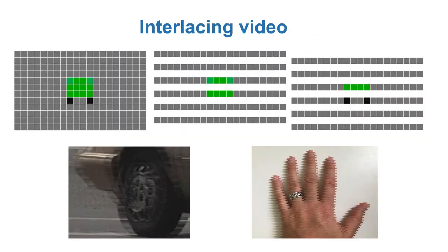Interlacing, as you see here, is actually not a major problem for production sensors in automotive applications. Such sensors are just not used. However, it is still not uncommon that interlaced cameras are used in laboratory or field data collections. So what is it? Well, the basics of interlacing started in the 1920s, with the aim of minimizing the bandwidth needed to send images or videos wirelessly.